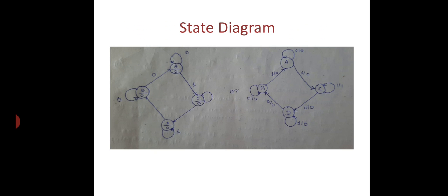The first design step is to draw a state diagram. This is also called a state graph, which looks as shown in this PPT. A state diagram describes the behavior of a single object in response to a series of events in a system. That is, it represents the relationship between the inputs, present state, next state, and the output of a sequential circuit.